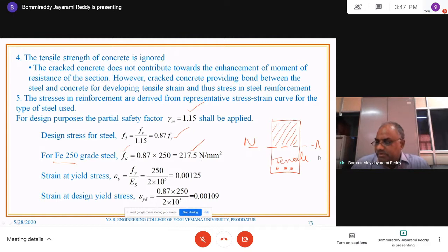At that stage, what is the strain? Strain at yield stress. Yield value means 250. So Fy by Es is the strain, and the modulus of elasticity for all the steels is the same, 2 into 10 power 5 Newton per mm square. So the strain at yield stress is 0.00125, whereas the strain at design yield stress...